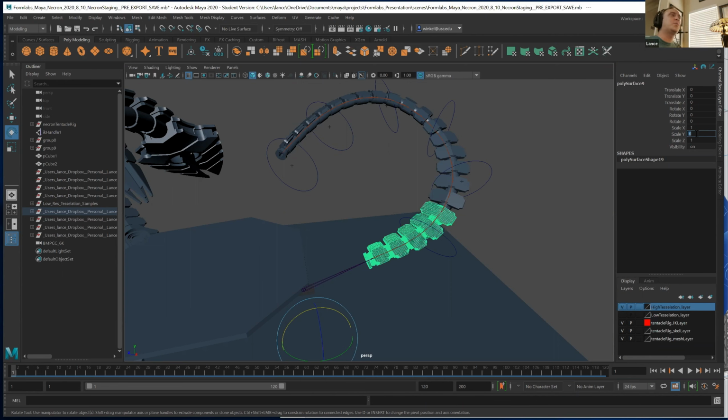And when you go to export your model, you might notice that it looks like it was flattened by a cement truck and became a pancake. Okay, so you want to make sure that you don't have any non-one scales. You want all of your scales to be 1, 1, 1. That's 100%, 100%, 100%. Okay, now I'm going to do this. I've got nothing, no problems there.